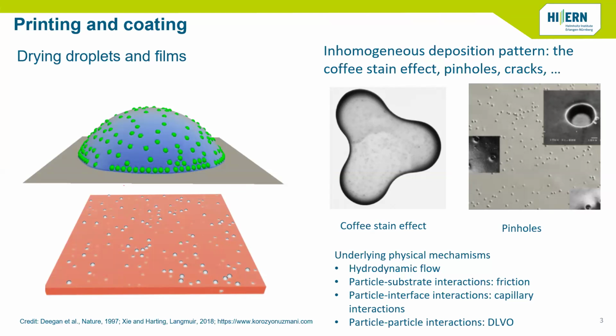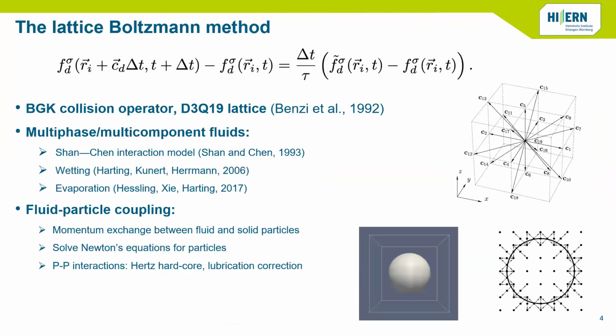So to understand this process, we need to gain insights into hydrodynamic flow, particle-substrate interactions and the friction between particle and substrate, also the capillary interaction between particles, as well as the DLVO interactions. And we use lattice Boltzmann simulation to investigate these systems.